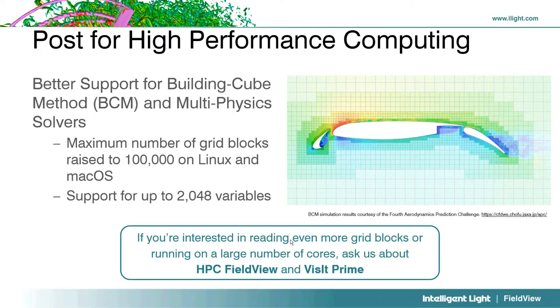And for our users running on high-performance computers, we've been making further improvements. For instance, we've raised the limit on the number of blocks or grids that you can load in FieldView. It's been raised to 100,000, which is really important especially for customers in Japan using new types of methods called building cube that we see appearing in a lot of solvers over there. We've also increased the number of variables that can be supported in FieldView, raising it up to 2,000. And that's especially interesting if you're doing multi-phase, multi-species simulations. The number of variables goes up very quickly.